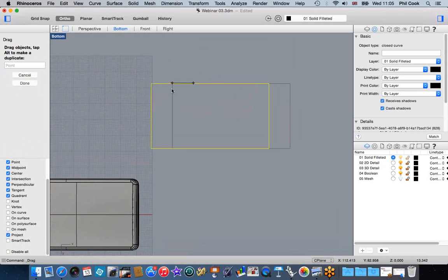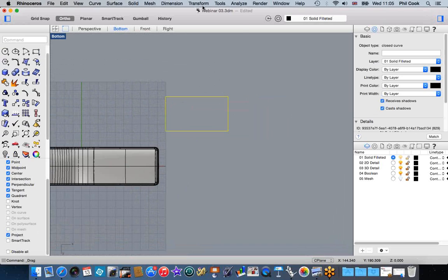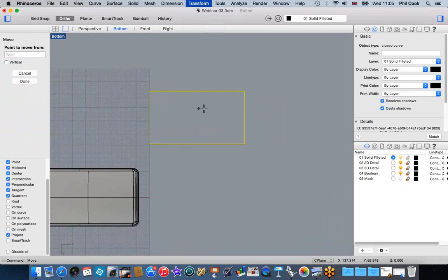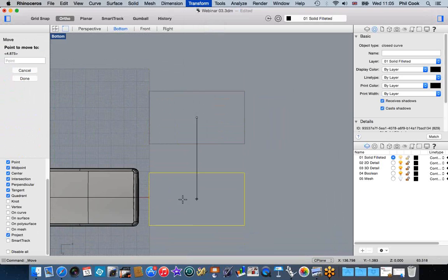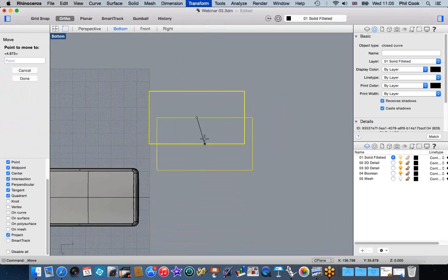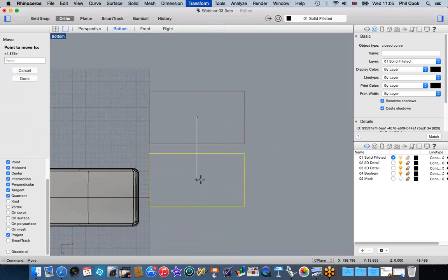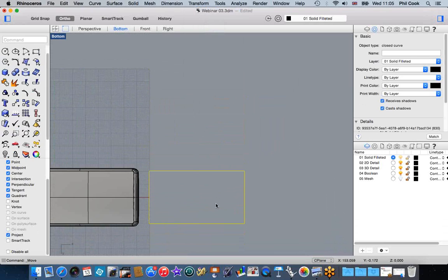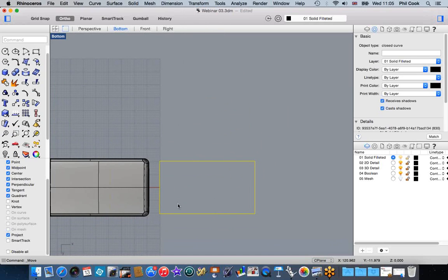for my geometry. So I'm going to move this now from the center line down to align with my x-axis here. To do this, just start the Move tool, hit the Tab key, and then type in 0 to put this on a 0 along the y-axis here.